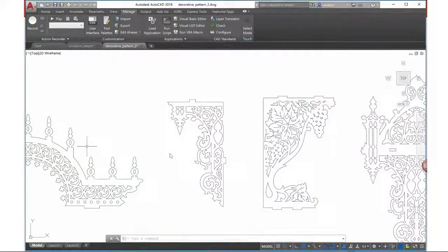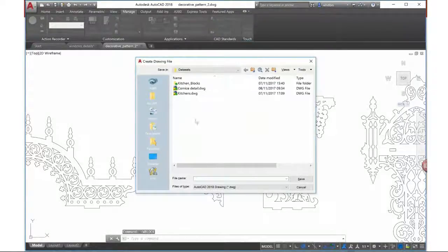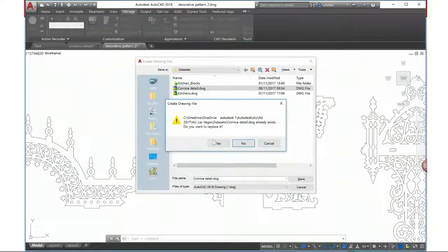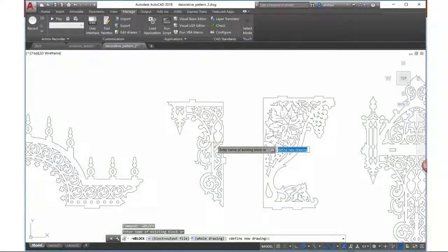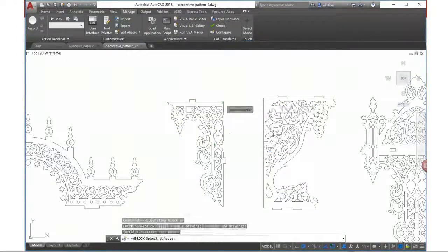The next piece on this is going from 2D to 3D in one hit. Here I've got an architectural detail. I'm in AutoCAD, and I want to make this 2D architectural detail a 3D architectural detail. So I'm just doubly blocking that, just that one profile out, and then we'll go into Revit.